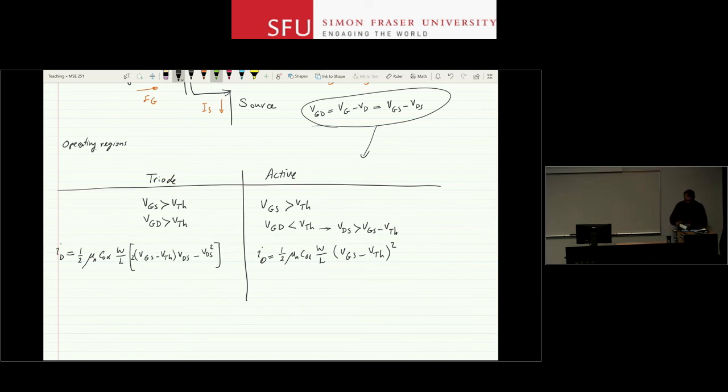Great. And then we didn't talk about it, but obviously the first operating region where we started was when VGS was less than VTH. We didn't explicitly talk about it, and VGD was less than VTH, right? If both of the voltages at the drain and source ends are less than the threshold voltage you need to establish a channel, obviously the device stays off, two back-to-back diodes, and ID remains 0, and then we know IS is also 0. And this is your cutoff region.